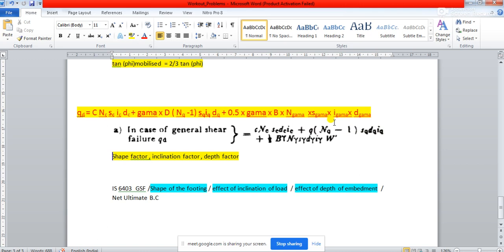However, if you go with that RW1 factor also, it will not impact your bearing capacity calculation much, because I have explained that the effect of RW1 is nothing but to reduce the value of the bulk unit weight or the saturated unit weight of the soil when the water table rises up to the base of the footing, and the soil is either fully submerged or partially submerged.